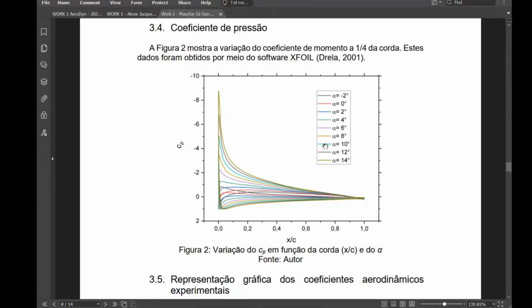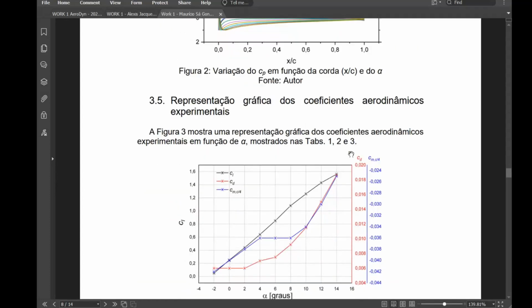they are not exactly precise to simulate flow separation from upper side of the airfoil. So you could simulate also 14, which is exactly stall angle of attack, but if you simulate 12, also acceptable. Even at 12 degrees of angle of attack, you will see small flow separation region. This we can see, I think, from this plot right here.